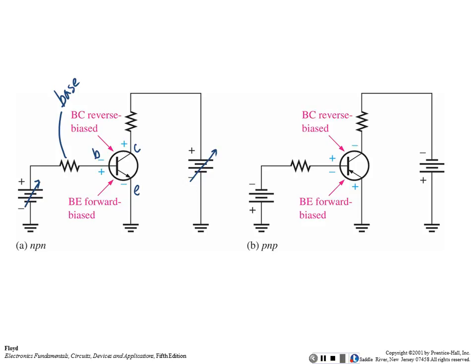Because it's a P-N junction, right? You understand. And as soon as a P-N junction turns on, it's a short circuit. It's a closed switch, right? So as soon as we get above approximately 0.7 volts for a silicon transistor, that switch closes right here and we start having current flow. Well, if I don't have anything in there to limit the current flow, then we could burn the base emitter junction up in no time at all, right? You understand? So we got to have that resistor.